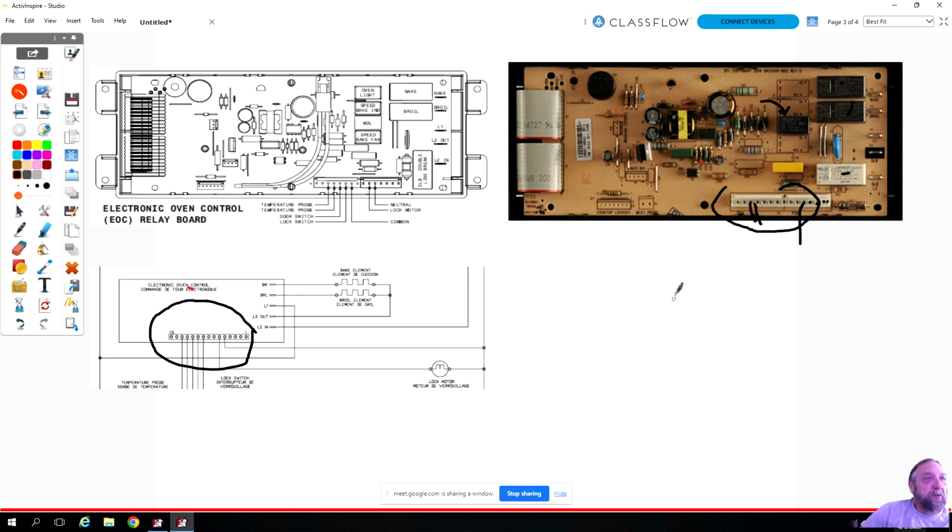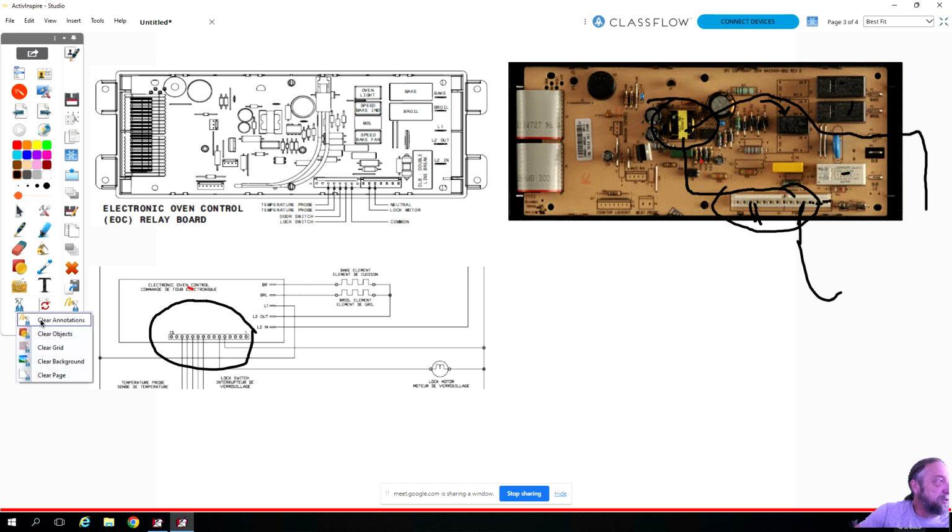Okay, so going back to what I was saying, this was the control board here, and this was the neutral wire, the 5th pin over, 1, 2, 3, 4, 5, and our power wire went in here to L1, and this is where I set up the power coming in. This is the transformer right here. So if I was to flip this board over, if you ever looked at a control board, you see all these lines, they call them traces. And those are like wires. They're the ones that are soldered on the board and they carry the power to that transformer. So I just showed you the plug over here is the same as that plug. I apologize for not catching that mistake.